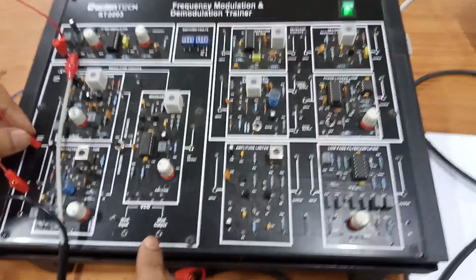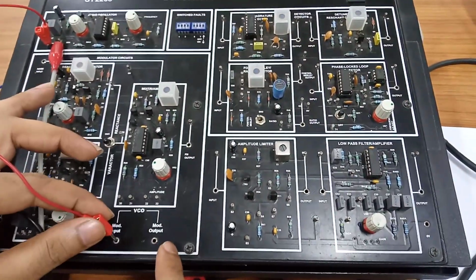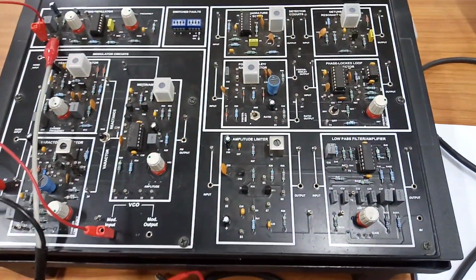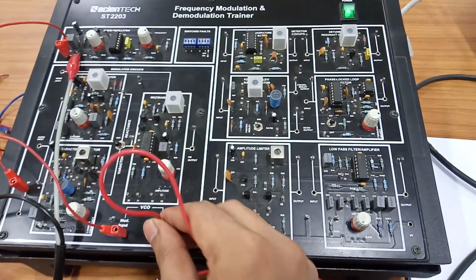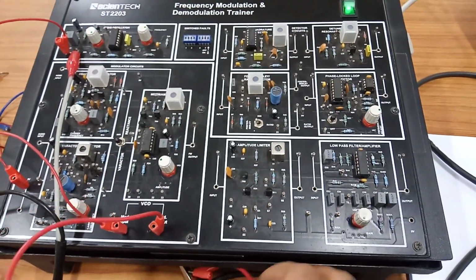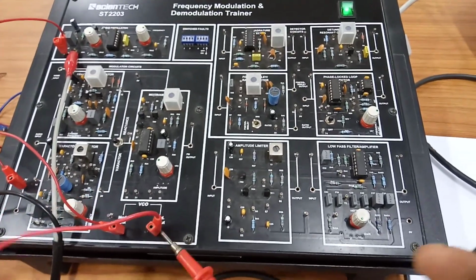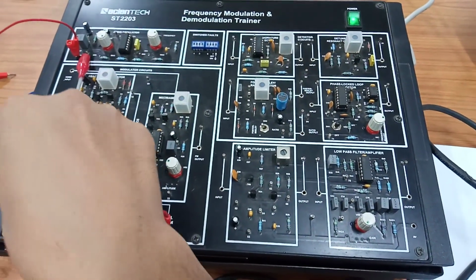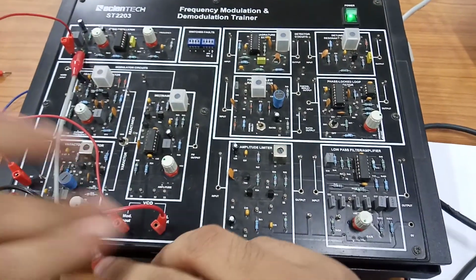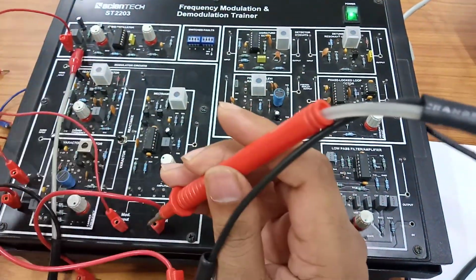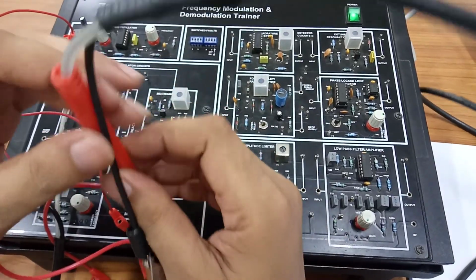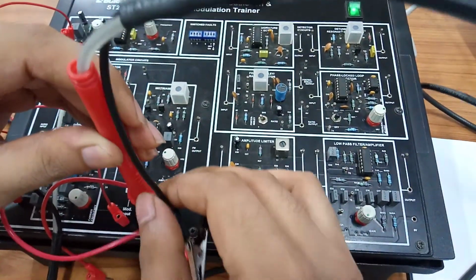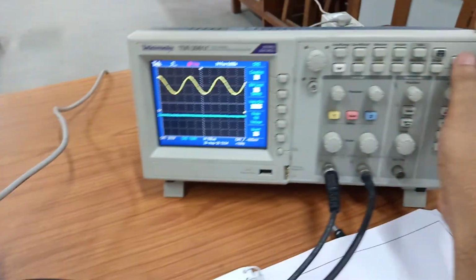Here we can directly see the modulated wave very clearly. The voltage controlled oscillator is a circuit inside, so we can see the modulated output from here. So I am connecting this to channel 2. This black probe is the probe for channel 2. I am connecting this ground here and this particular thing, so that we can see how the modulated wave looks like. I'll run the CRO so that we can see it. You can see over here, if I run this CRO,